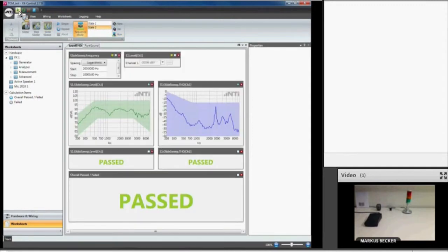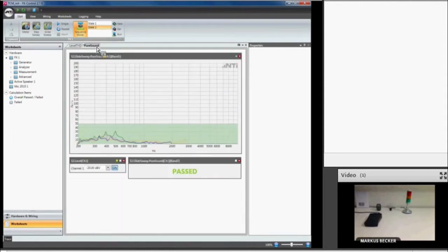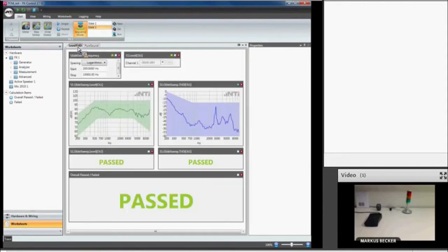Maybe you have noticed that the second glide sweep had a higher level. I intentionally selected this higher level because this is a very typical application: in a speaker test you would apply a higher test level for rub and buzz detection rather than the standardized level for frequency response and distortion level. You also see the outcome, all the tests are passed and everything is fine.